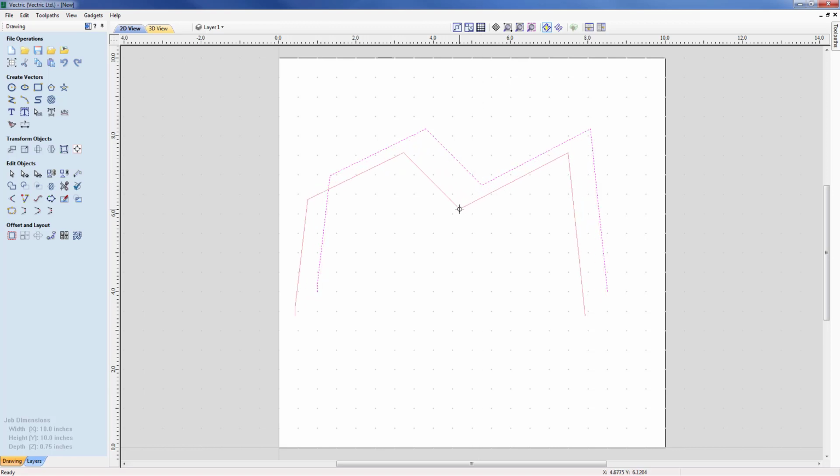Okay, so I've just started to move it around. I've got my left mouse key depressed, and I will now want to go maybe 1 in X, so I can go 1, 3, and hit return, and that will have moved it up in Y by 3 and along X by 1. So I'm just going to hit Control Z to bring this back now and back on the screen. So that was an incremental distance in both X and Y at the same time. So that was just 2, 3.